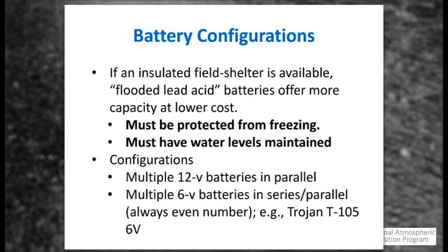For cost basis, if you have some sort of insulated field shelter, we do recommend flooded lead acid batteries. They offer significantly more capacity at a much lower cost. However, they must be protected from freezing. So southern sites would be fine if freezing is not an issue at your site, and you must regularly check the water levels. That would be every few months. So various configurations are possible.